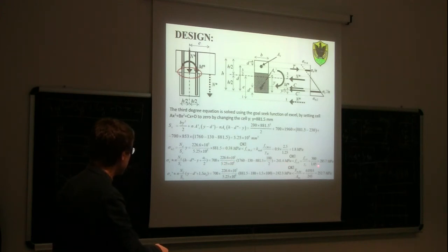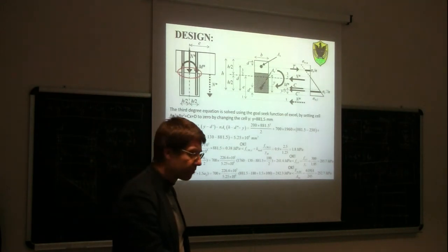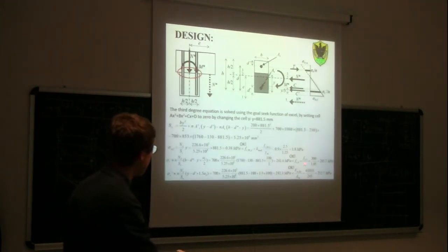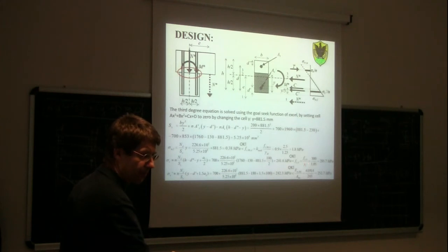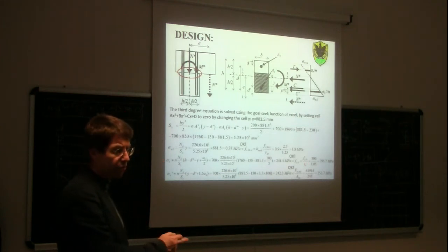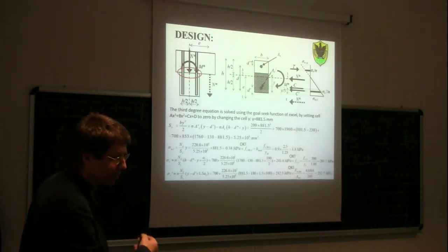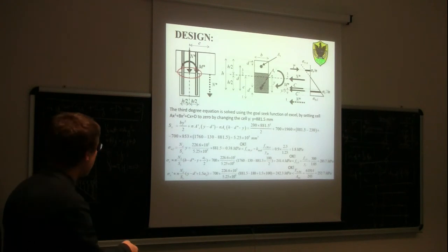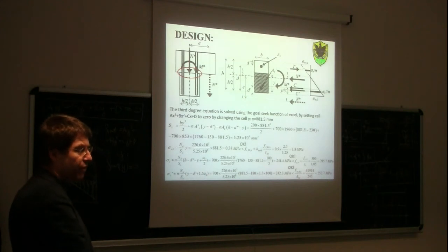So this is much closer to failure than this. If we had the possibility to redistribute the stresses after the failure for buckling of the compressed rod, we would get the failure in tension of the tensile rod, and only at the end, the failure for compression perpendicular to the grain. Okay?